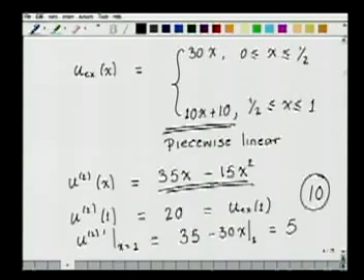So we have an error of 5 in the derivative of the approximate two-term solution, and this error is 100%. Now in most of our computations, we are not interested in the value of the solution. We are mostly interested in the derivatives of the solution because we want to obtain the strain as well as the stress information out of this computation. So you see that this is a disaster as far as the numerical solution is concerned.